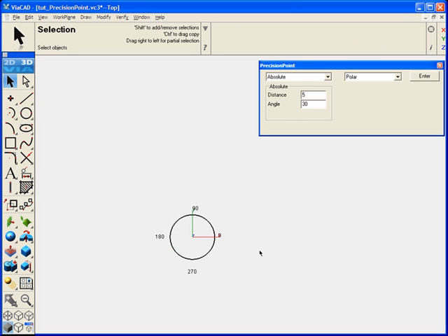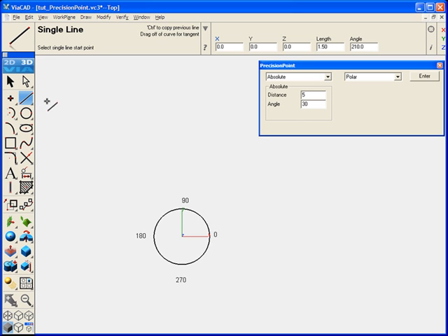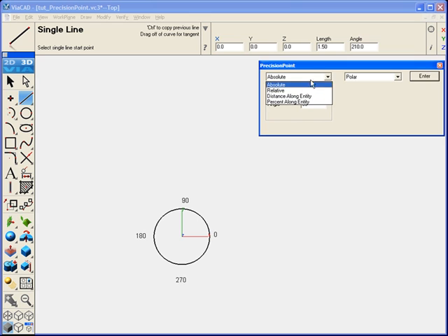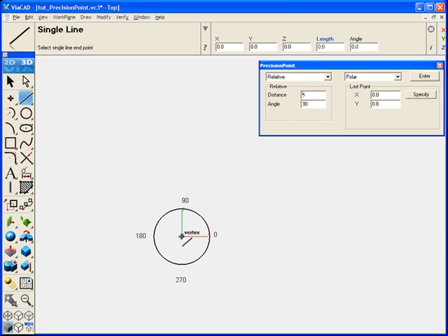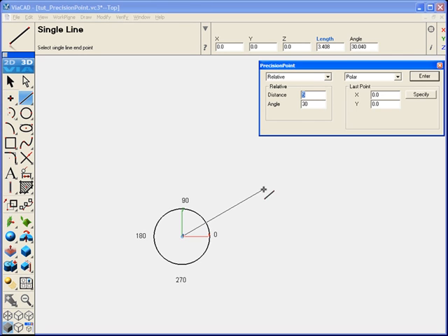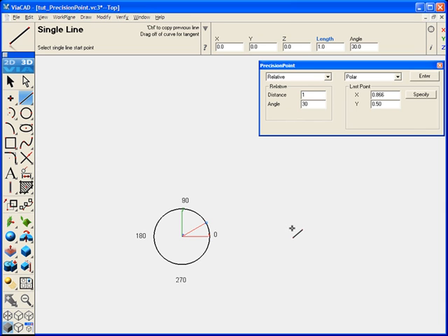Now let's delete these. In other cases, you know the length of the line, you know the angle of that individual line, but you don't necessarily care what angle that point is from the origin. So we'll set our first line, 1 inch at a 30-degree angle. Now we'll set another line. Just assume that that polar diagram is oriented around the point that we're at right now.